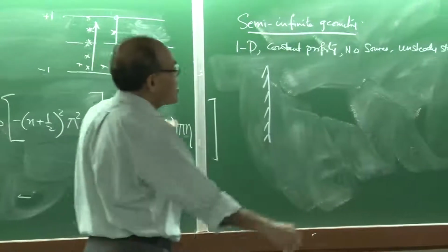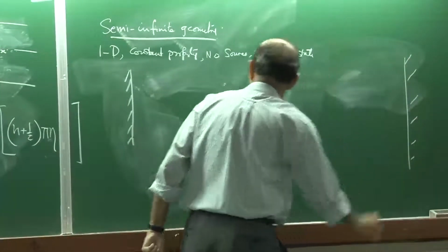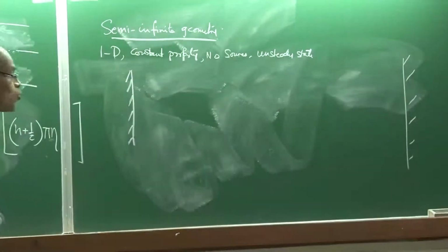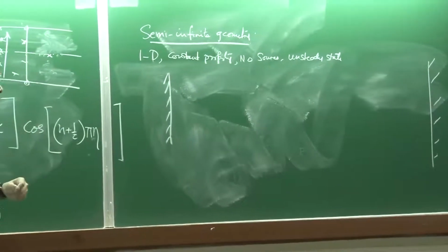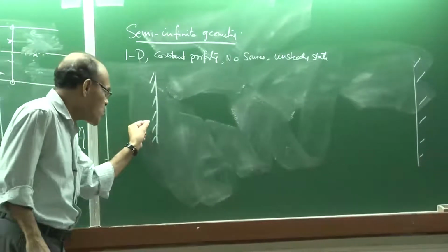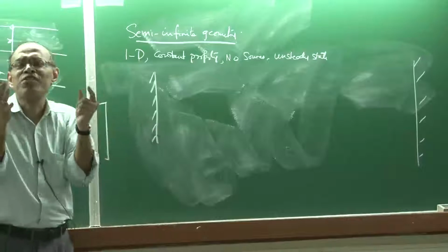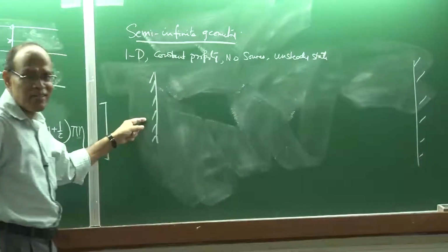Suppose this is a steel bar, a steel slab. You may not know the value of thermal conductivity, etc., but you know, because you are a metallurgist, the value of diffusivity. You can imagine that I have a process which is 3 hours long, the slab is this thick, and I want to carburize it.